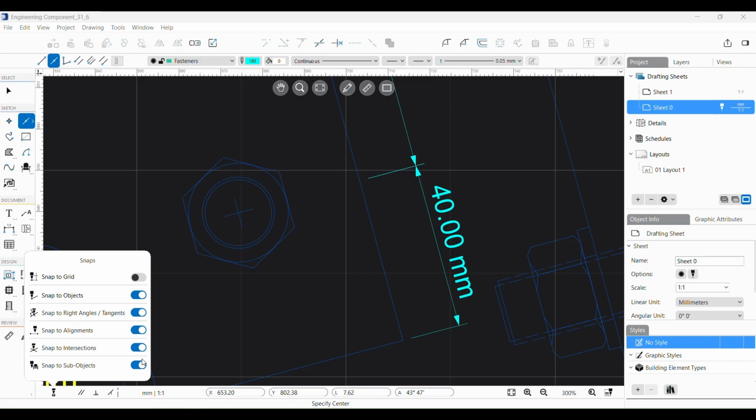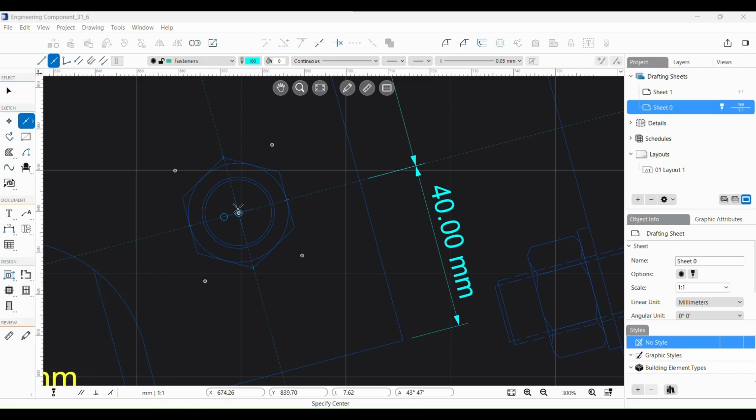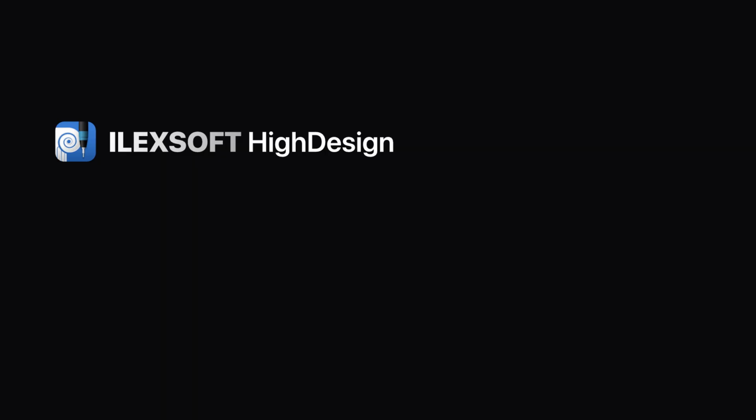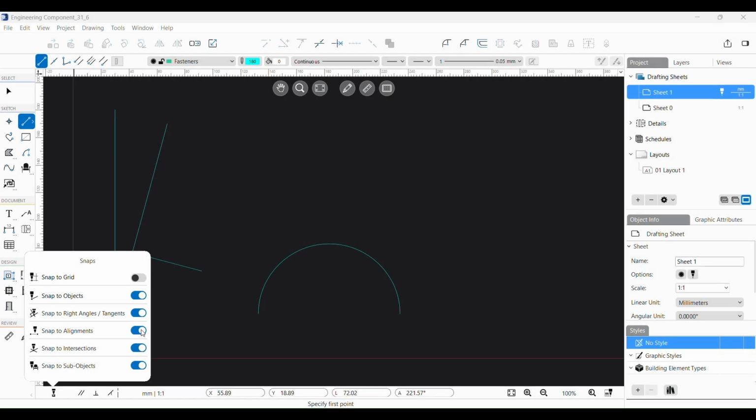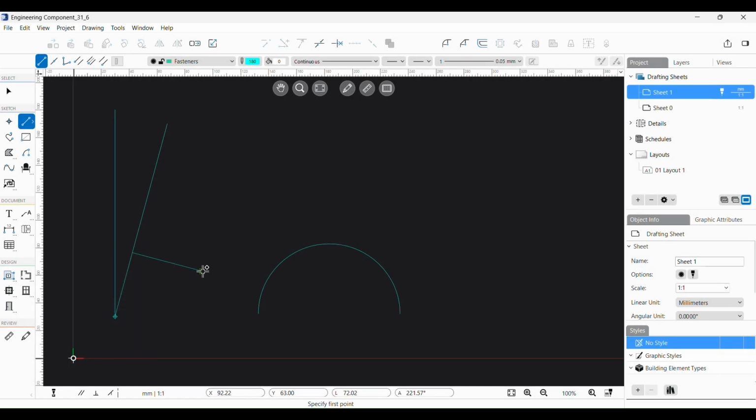Snap to subobjects. Allows to snap to the objects inside the instances of symbols inserted into the project and inside the viewports inserted in layouts. When the pointer snaps to one endpoint of an object, that location is stored as current origin of the temporary guides. The guides are displayed when the cursor is on the x-axis or y-axis of that datum point. The pointer also snaps to the intersection of the guides. The intersection is highlighted with one point and both the guides visible.